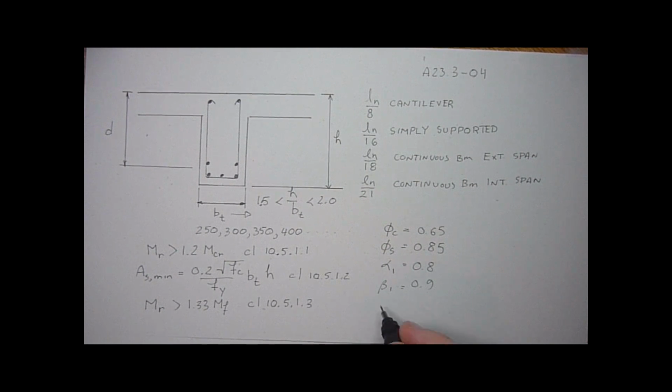Also, a good rule of thumb for reinforced concrete design for beams is that they generally range from 25 MPa, and we can either select 25 MPa or 30 MPa. It really doesn't make a difference when it comes to moment resistance. It's not that sensitive. It's more for other issues, quality issues of the concrete. So you generally choose one of these two in the specs for the strength.